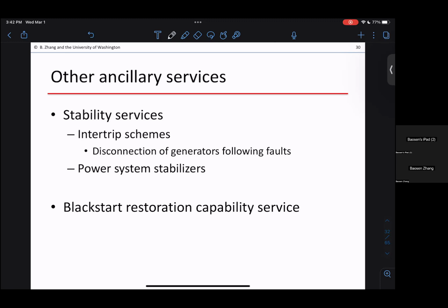Right, so there's some equipment you have to run to get a generator started. The best example of that would actually be hydro. So you cannot black start a hydro system. The reason is you need some power to open the valve on the hydro system. You need power to adjust that. You need electric power for that. A hydro system wouldn't start on its own. Same thing for nuclear, you need to cool the nuclear power plant, and it can't cool itself. Okay, so there are not many plants that can actually do black start.